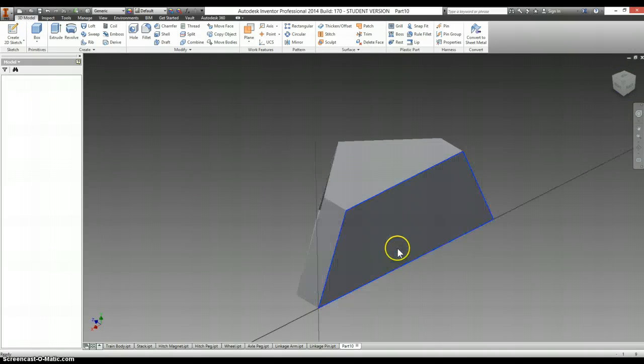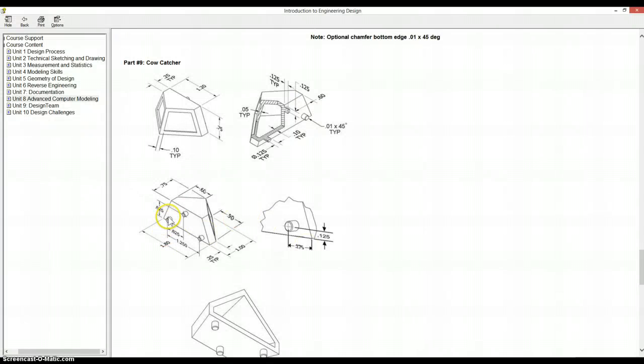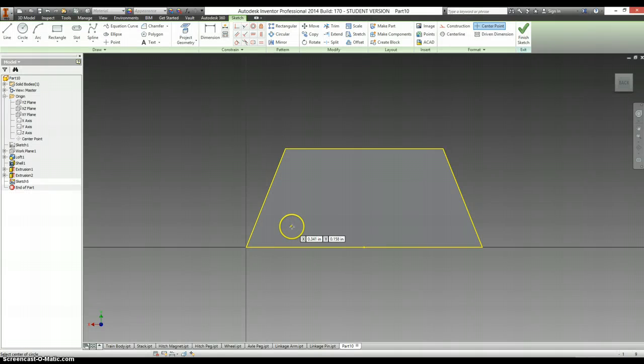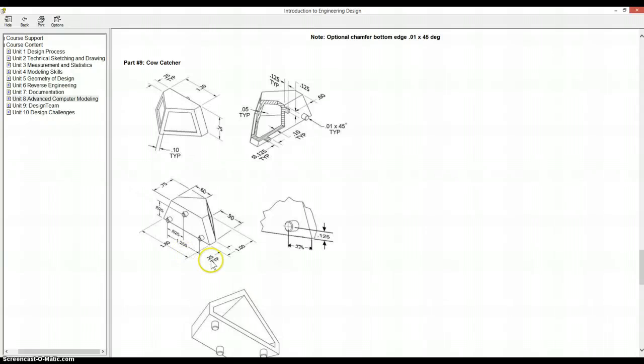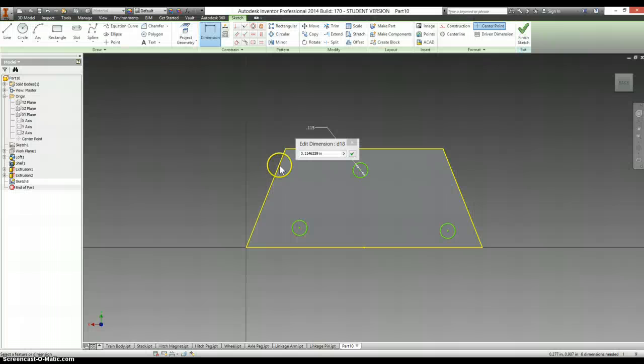Now I just have to make a new sketch on the back side of this. So we have three little circles we're extruding out. They each have a diameter of, where's my diameter? 0.125. Let's draw three circles, set them all to be equal. Oop. Clicked on the wrong line there. And then I'm going to dimension one of them to be, what do we say? 0.125.